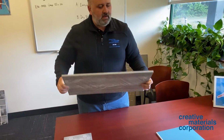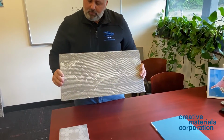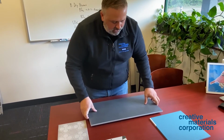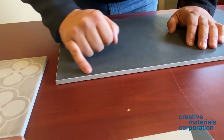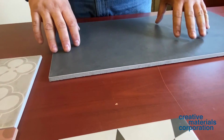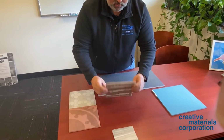So here is a glazed porcelain tile that's meant to look like a slate. It's got a black surface on it, and they put pigments in the back to have it be a black look. It still has that engobe layer in between, and if you zoom in here, you can see around the edges where it's rectified, you can almost see that white engobe layer coming through. Okay, that is a glazed color body versus a glazed non-color body.